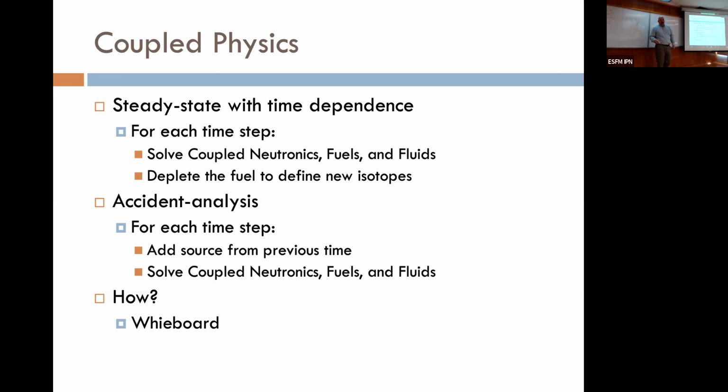The reactors that have been mostly designed, you would see that at Westinghouse, at General Electric, in the US Navy, there were buildings of neutronics and buildings of thermohydraulics. And they would literally write code to do neutronics, given temperatures, and then pass a file and say, hey, here's my output file. This is my power distribution. And the thermohydraulics people would take that file and put it into their own input and then run their own calculations and say, here now are your temperatures, your densities, your velocities. And so this is how engineering was done.